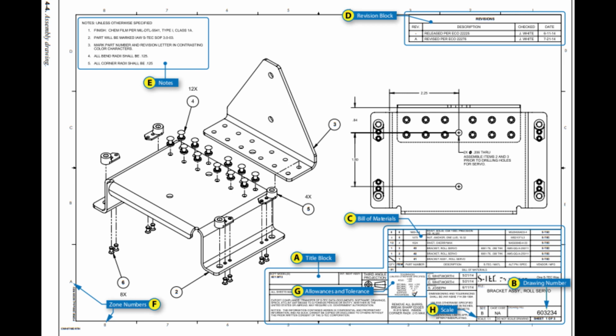In aircraft, many parts on the left side are like the corresponding parts on the right side but in reverse. The left-hand part is always shown in the drawing. The right-hand part is called for in the title block. Above the title block a notation is found, such as 470204-1LH shown, 470204-2RH opposite. Both parts carry the same number, but the part called for is distinguished by a dash number. Some prints have odd numbers for left-hand parts and even numbers for right-hand parts.